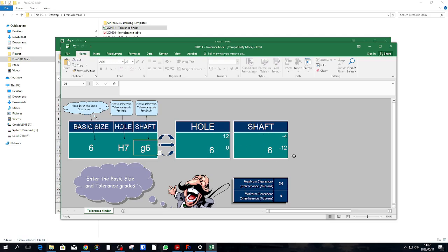Right, so for the shaft, here we can see it's minus. Sorry, I'm wrong. This is 8 millimeters. Yes, okay, so yes, it's minus 5, minus 14. That's for the shaft. The hole is obviously not relevant. We're looking at this tolerance over here. Minus 5, minus 14.